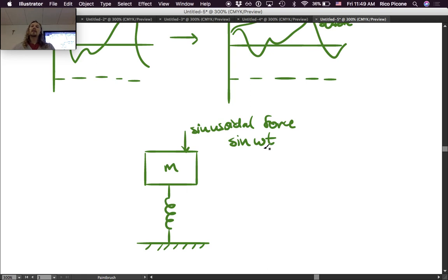At most frequencies, the output is bounded for this system. So it's marginally stable in the sense of the free response as well, right? You let it go, it never damps out, it just oscillates. And if you put in a sine forcing at any frequency other than the one special frequency, then it's fine, it's bounded too. So it's BIBO stable for most of the inputs.